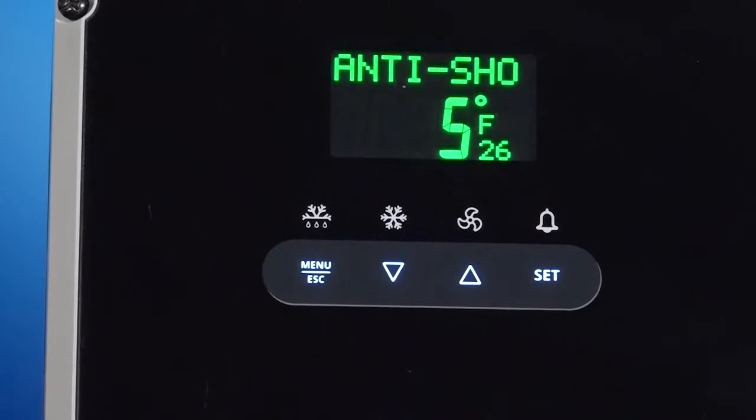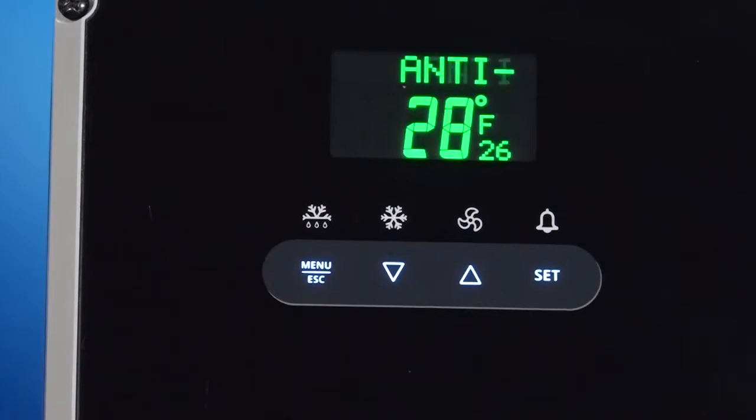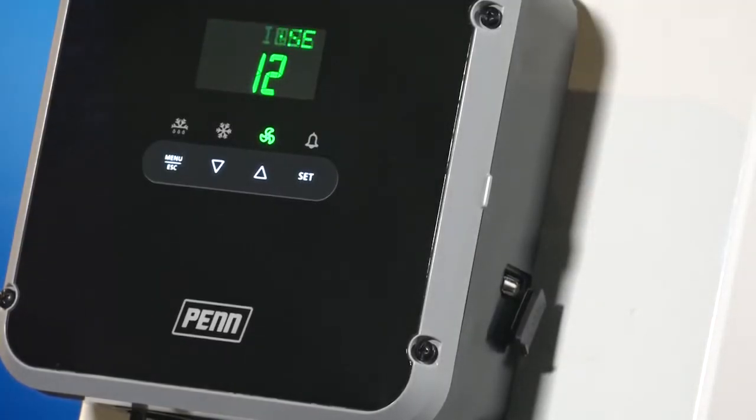Depending on how the alarm conditions were set up, the alarm could be permanently silenced or just delayed until the condition is corrected. When an alarm condition is triggered, the A525 control will record and store the event. The information that will be stored is the date and timestamp of the event, the type of the alarm condition, and the alarm threshold. The A525 will maintain the past 100 events. The event log can be downloaded for record keeping via the USB port on the A525. Please review the video on file downloading and uploading for additional information.